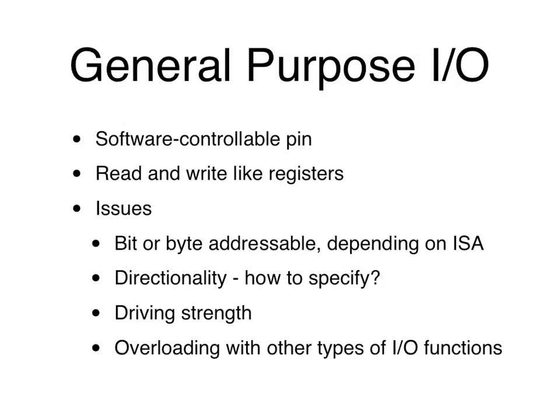From the interface point of view, you can treat general purpose I/O ports as basically what's called software controllable pins. And by pin, I mean you can actually see and probe it, right? Whereas if it's a register, it's inside the chip. You can't do anything to it. You can't look at it. Whereas a pin is exposed. That's real hardware with a voltage on it. So one simple definition is it's a software controllable set of pins.